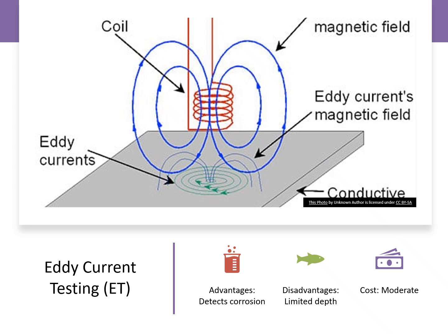It is particularly effective for identifying cracks and corrosion, and material thickness variations, but one of the key advantages is that it requires minimal surface preparation and provides immediate results. However, again, like many others, the depth of its penetration is limited, and it requires calibration and trained personnel. The cost of this is moderate, making it a practical choice for applications such as aircraft skin inspections and structural assessments.